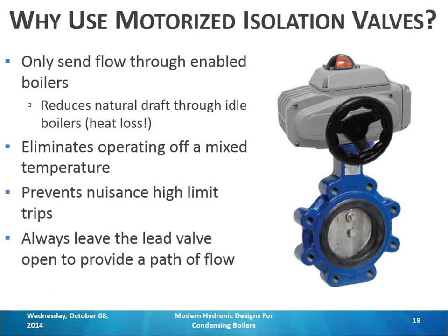So we have 100 coming back. The last boiler is running, so these three are idle. We have 100 going in and 100 going out, 100 going out, 100 going out, and then this boiler is providing 140, but then downstream, our temperature is much lower than 140, so the active boiler has to supply a very high temperature water, which might exceed its high limit, often does.